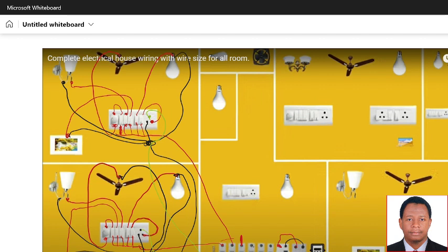circuit breaker. This circuit breaker is going to control this house, so the living room and the washroom. I connect the live to this socket, connected again to this socket, connected again to this socket, this one and this one. Now if we see, there is a difference because this socket board doesn't have the regulator. Why? Because here we are not going to control any fan.